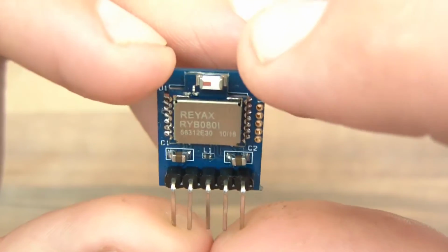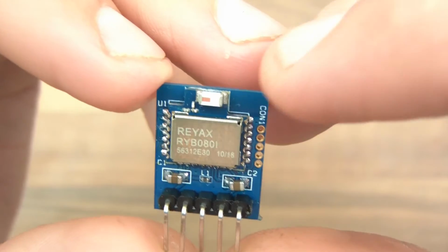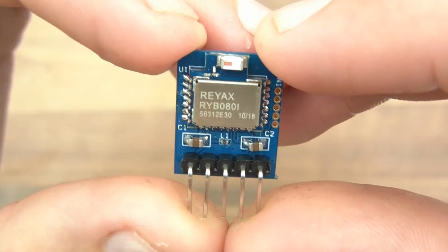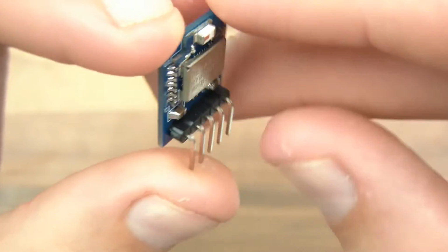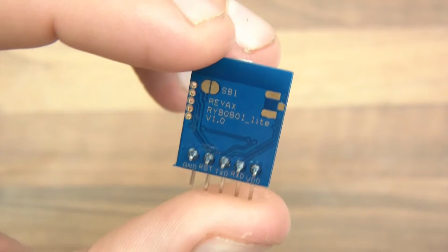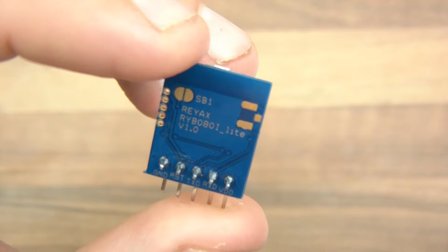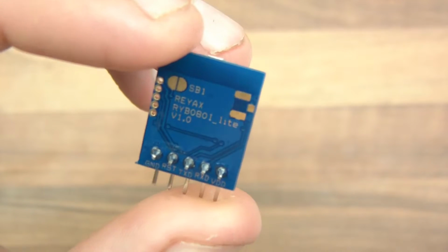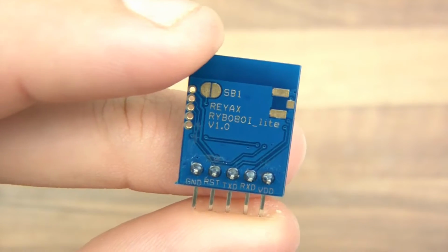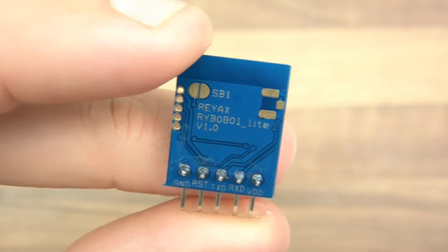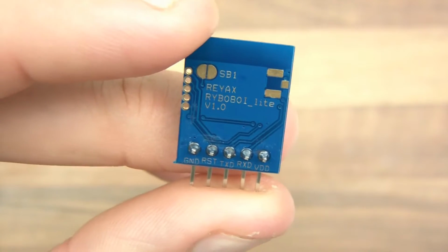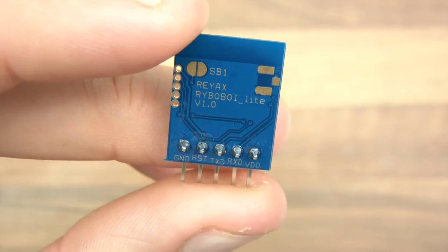So anyway, I told you that this had a microcontroller in it already. How do I know that, and why is that important? Well, this particular Bluetooth module is quite interesting because look at the pinout. It's got ground, reset, TXD, RXD and VDD. That's quite special because that makes this thing a serial device, and basically all you do is power it and talk to it. There's nothing else involved. You don't have to program anything. It's really simple. Power it and talk to it.